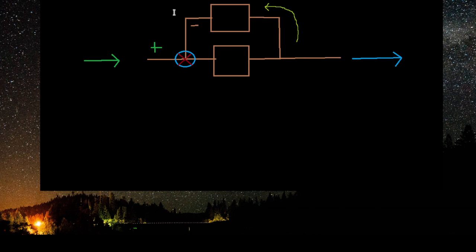Okay, so there's a signal that continues to rise and then it levels off. That's similar to a capacitor charging. Then you have a quick charge where it bounces up and down between the steady state value. So you have what's called initial conditions in the system. And then there's a steady state value where this system becomes stable if the differential equation states that determines limits in the system. So you've got a formula for a transient response, and it talks about critically damped, underdamped, overdamped.